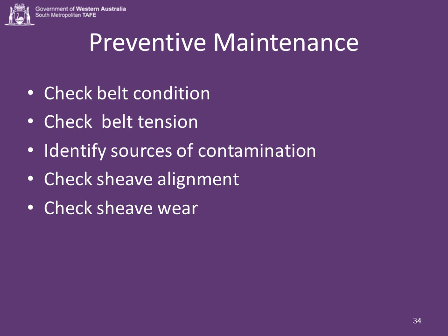Belt preventive maintenance. Check the belt tension using a belt tension gauge. Measure the deflection and tension of the sides of the belts. Be sure to write tension and deflection specifications for the mechanic on the preventive maintenance checklist.